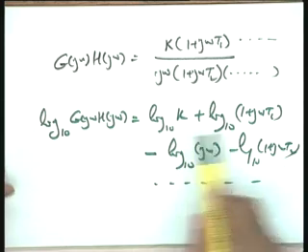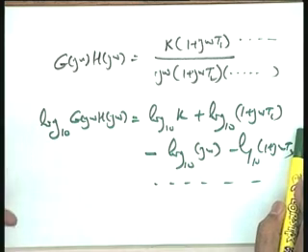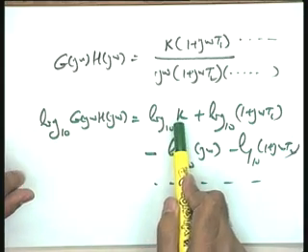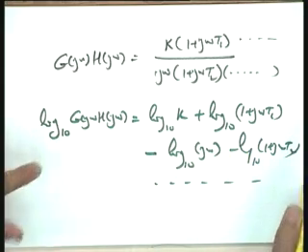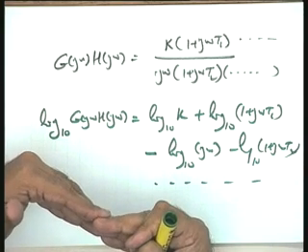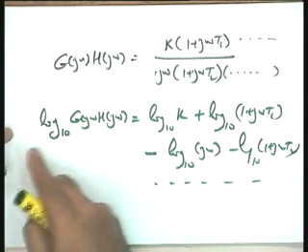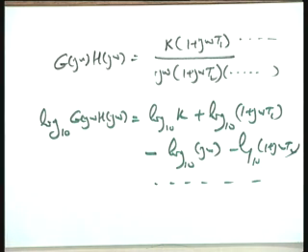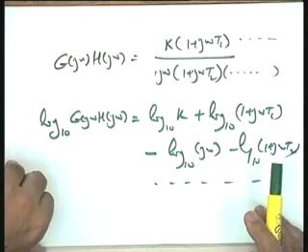Please see, not only the logs, the additional contribution from Bode is that the plots of all these terms are more or less straight lines, and therefore addition of all these straight lines becomes easier, and hence the overall plot is easily available to you. Okay? So, this is the major thing, that the multiplicative terms become additive terms if you take the log operation on the transfer function. So, what I will do now, I will take the magnitude and phase separately.